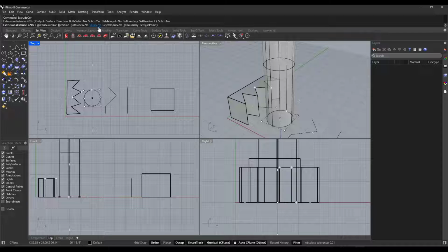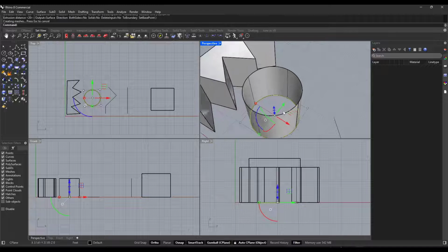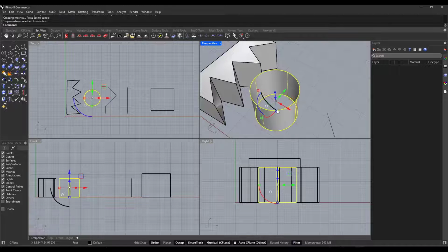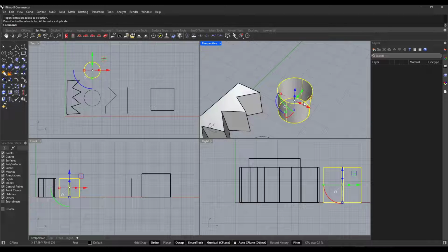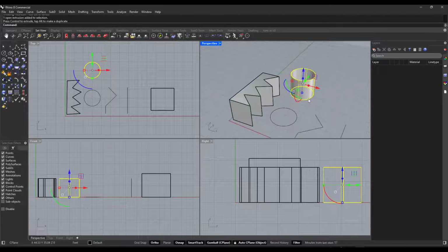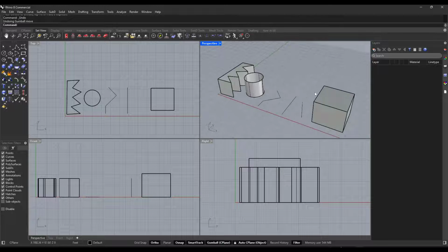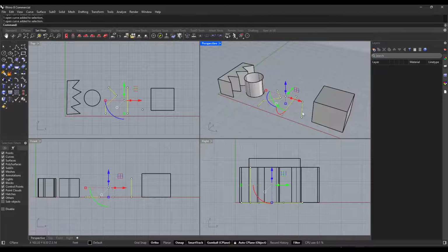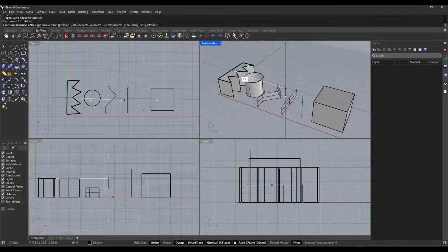And so if I uncheck the box for solid, what that's going to do is extrude the curve, but it's not going to cap it like this. Then you just get this extruded 3D shape right here, but there's no actual fill in here. And so depending on what you're trying to do, that could be good or bad. In this case, I would say it's just kind of an option, but you can use this in order to extrude objects to 3D. And notice how you can select multiple objects in here. You could type in extrude curve, and notice how I could extrude them all at once.